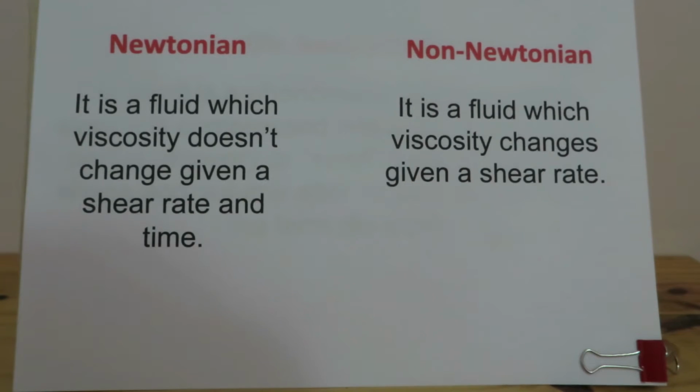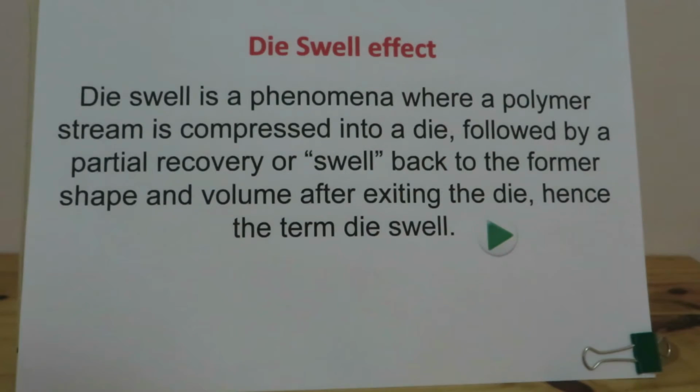Now we will see some interesting effects of non-Newtonian fluids. First, it is die swell. In an instance where a polymer stream is compressed by entrance into a die and is followed by a partial recovery of swell back to the form, shape, and volume of the polymer after exiting the die, hence the term die swell.